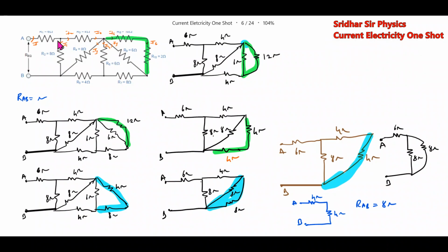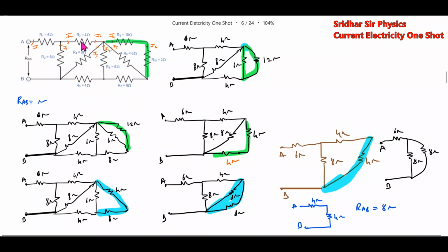Okay, kids. If you have a circuit like this, what you should do is identify the series parallels. First, branch the current. Where the current remains same, they are in series. Where current branches, they are in parallel. Like this, everywhere the series parallel. Where current remains same, current branches. With that, you should identify and replace that with an equivalent resistance.